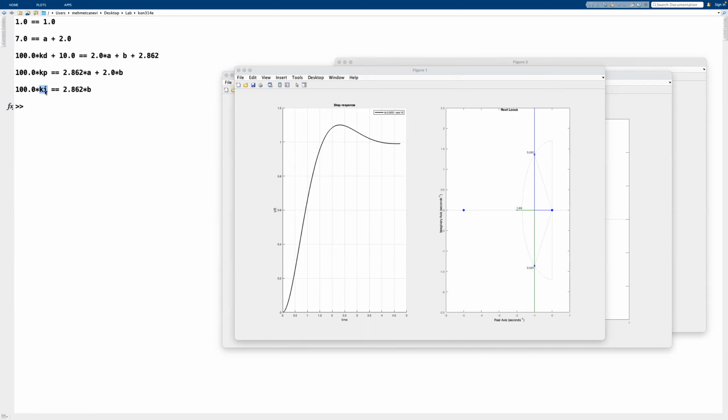The reason we do that most of the time is that there would be a direct relation between one of the coefficients of the residue polynomial and Ki. So therefore we have this relation here, which shows us that if Ki is positive, B is going to be positive. If I choose Ki positive and solve the set of equations in terms of Ki, then all those controllers will assign a set of poles to the desired point, and basically they will be stable in closed loop.